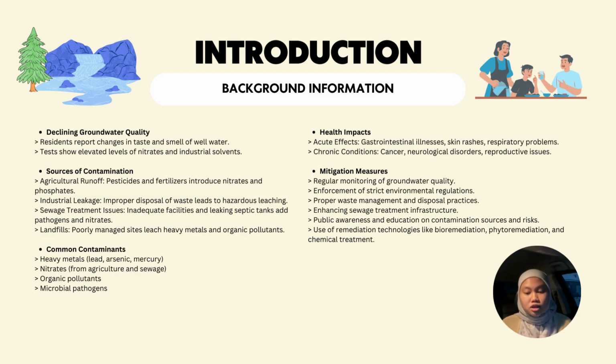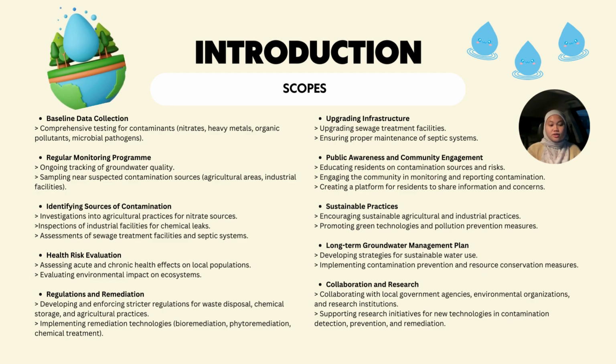The mitigation measures are regular monitoring of groundwater quality, enforcement of strict environmental regulation, proper waste management and disposal practices, enhancing sewage treatment infrastructure, public awareness and education on contamination sources and risks, and use of remediation technologies like bioremediation, phytoremediation, and chemical treatment.